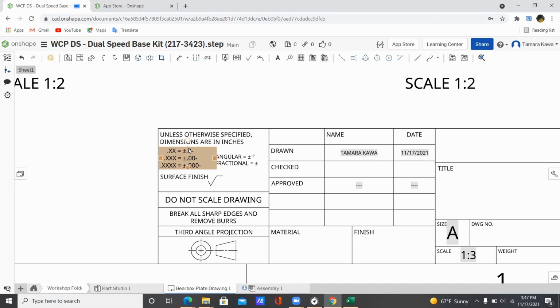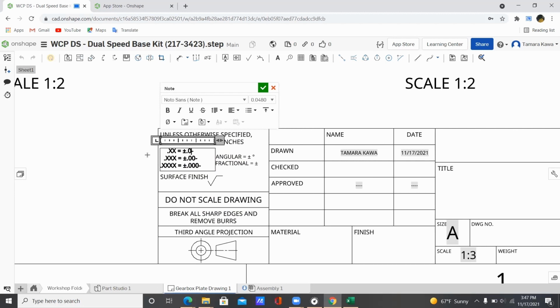Exactly. But if you have too loose tolerances, then if the fit needs to be really exact, you kind of lose that level of precision that you might need. Again, for the team, it's not so important. Yeah, milling is going to be important. Yeah. So CNC generally, you would generate G code and then send that out, but CNC was a good example. So you could change those if you want to be, say for 2 decimal places, I want a tolerance of 0.05, or for 3, I want 0.005.